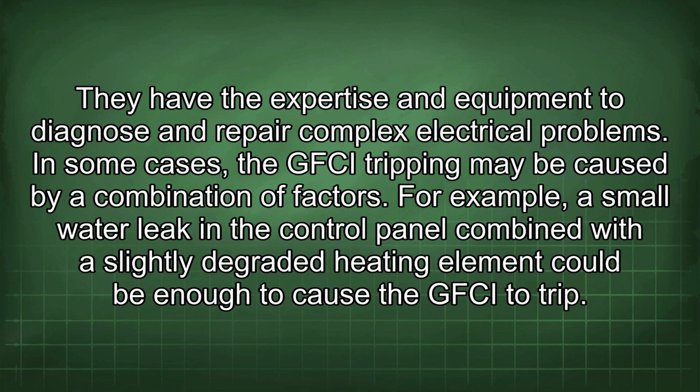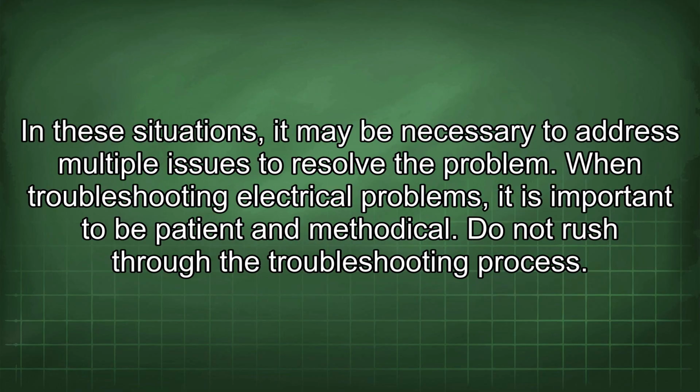In some cases, the GFCI tripping may be caused by a combination of factors. For example, a small water leak in the control panel combined with a slightly degraded heating element could be enough to cause the GFCI to trip. In these situations, it may be necessary to address multiple issues to resolve the problem.